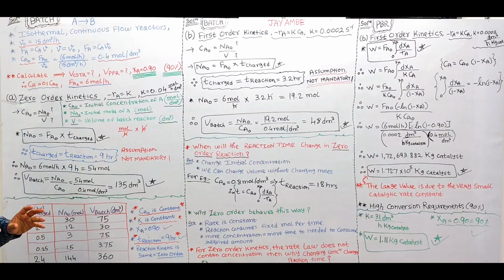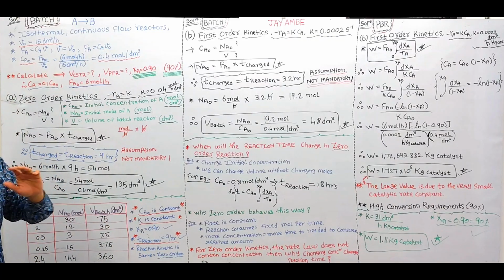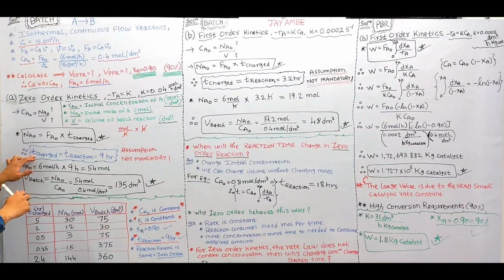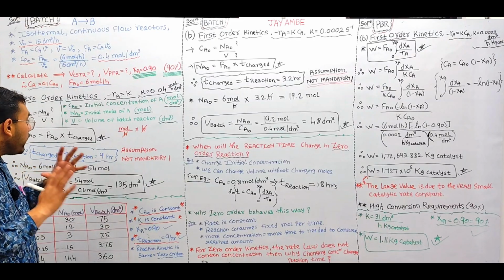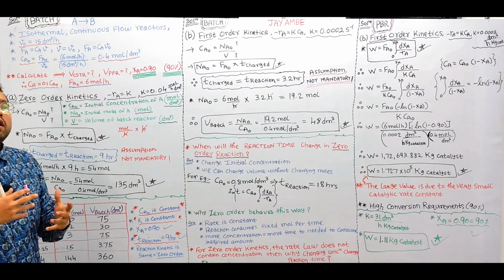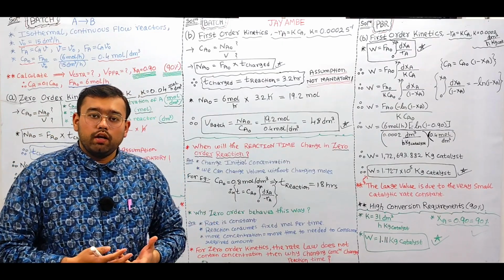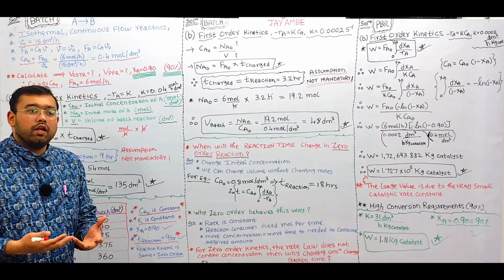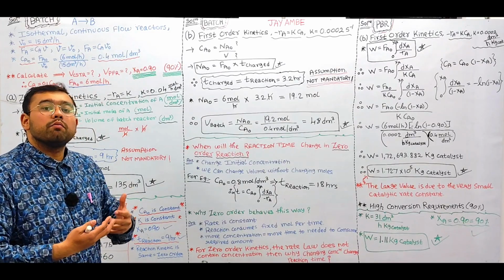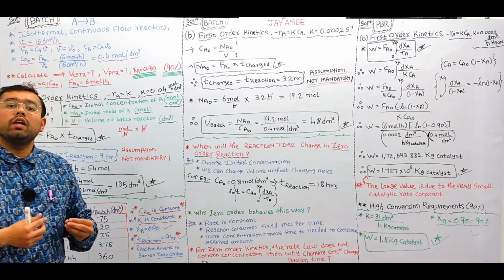Now, is this always mandatory? The answer is no, it is not mandatory, which means the charge time is not always equivalent to the reaction time. Why? The charge time depends upon the availability of the operating pump system. If the pump has the capacity of feeding at higher flow rates, then the charge time will be much lower.